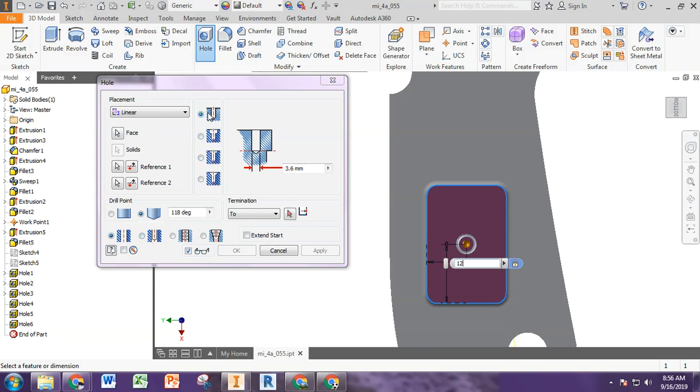A simple drill hole is basically like drilling through at a specified diameter, okay, which is this feature. If you put it on this feature, you can see there's a drawing of a screw going through the hole here. So what you do here is this would be what's called a clearance hole. Just waiting for it to load up. It sometimes takes a while.